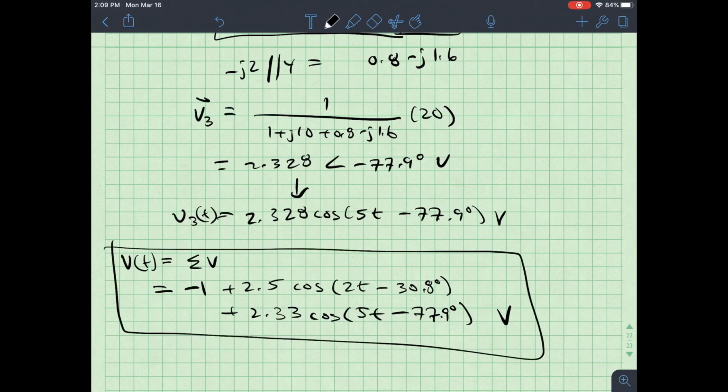If you had multiplied or added those phasors together, you would get a single sinusoid back, and that is bananas. Each of the frequencies for each of these sources needs to be represented in the final signal. And so if you would plot this signal, you would see that happen.